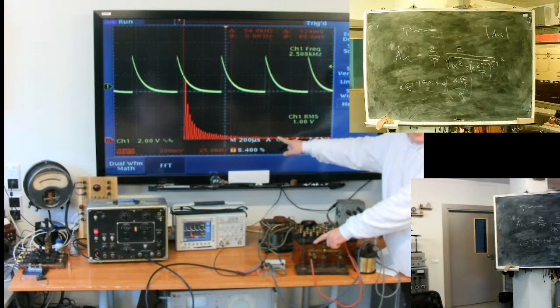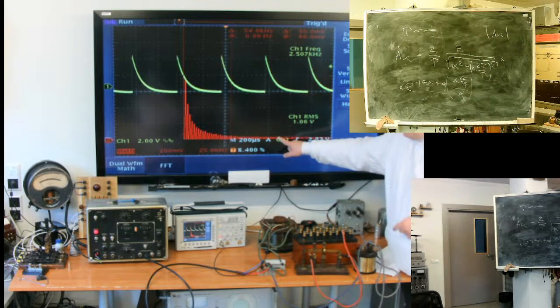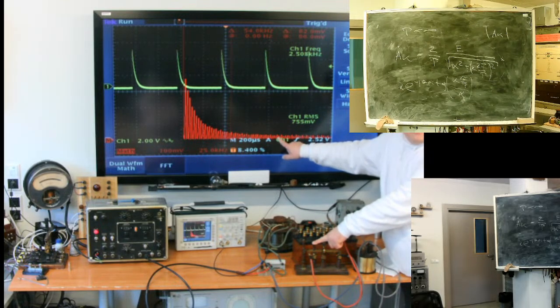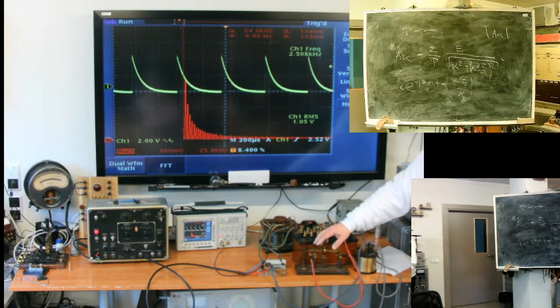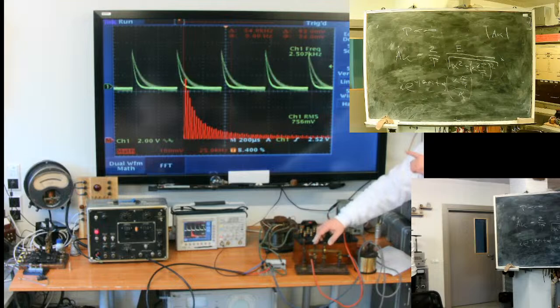Somewhere here you have a signal, let's say data transfer. At a slow rate, it was outside of the influence of the tail. You have a faster rate and everything fails. Disturbances from your inverter, from PWM, are in the range of your communication channel. EMC failed. See how the spectrum widens. The base is the rate of change.